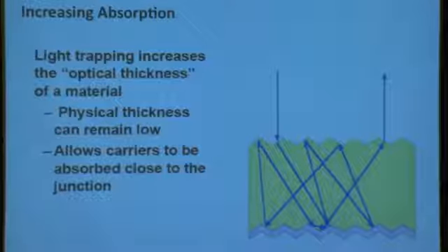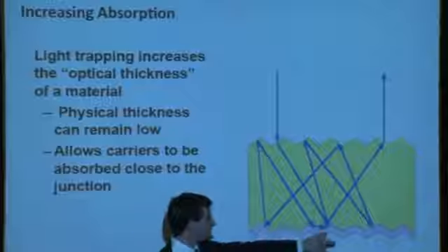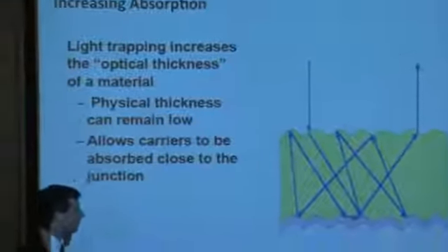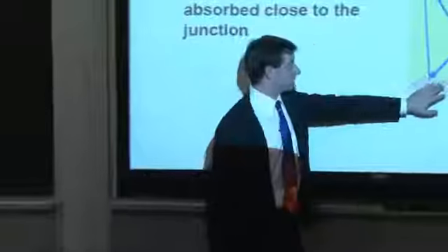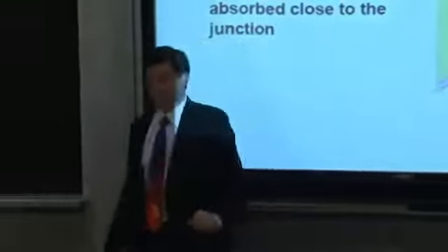In the case of silicon devices, oftentimes you have a dielectric material with a refractive index somewhere between 1.5 and 2, and that serves also to passivate the surface to prevent carriers from recombining on that backside.